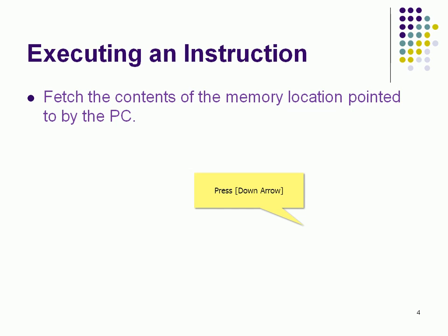With the help of this address and through the MAR, memory address register, it will go to the memory and search that location. After finding that location, the address which is provided in MAR, the current instruction will be downloaded from the memory and placed on the data bus, which has to travel to reach the CPU premises or processor. So that will be fetching the contents of the memory location which is pointed to by the program counter.